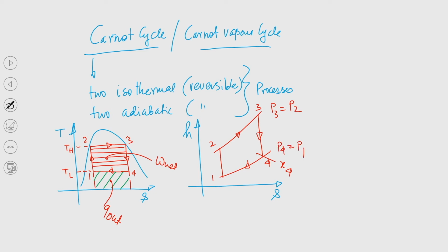Okay. So, what I would like to tell you, although you have studied two reversible isothermal, two reversible adiabatic processes which are shown in this TS and HS plane. Now, I have shown the points 2 and 3 on the saturated liquid line and saturated vapor line respectively, but now at least we should discuss. So, if we consider, then it can be shown that efficiency of the plant can be written in terms of 1 minus TL by TH, that I can derive now very quickly. So, if we try to discuss about the efficiency of the plant, this is x 1.